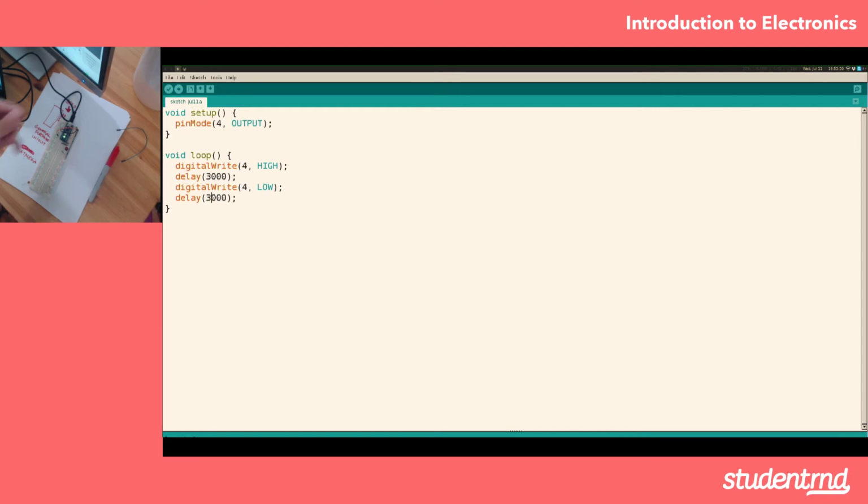So this is a transistor. You've probably seen a little bit. You could use this to turn on and off things. This is what's called a Mosfet, and this is probably what you would actually use. By hooking things up with a Mosfet, which is something you can look at online, you could have this tiny little Arduino basically act as a light switch that's switching on and off a much higher voltage, or a much higher current, or both, to actually drive a motor.